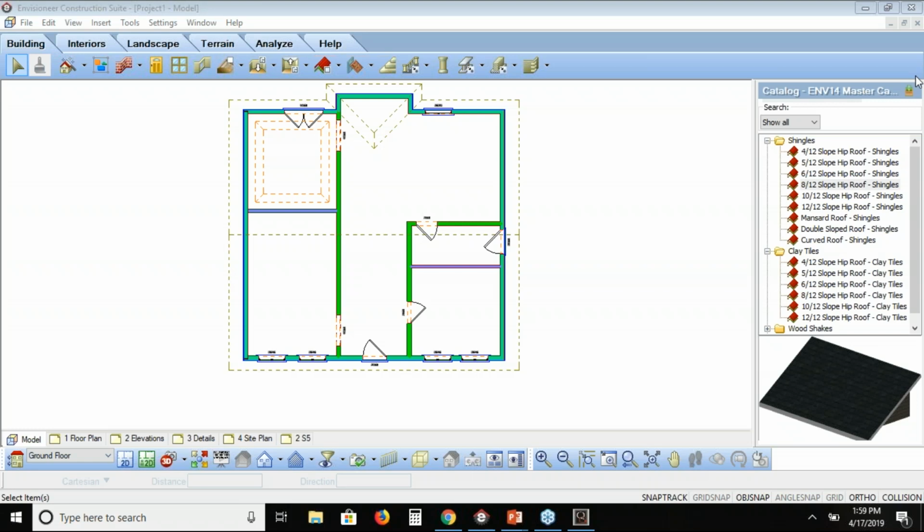Also, is it possible to frame the ceiling in a more practical way for span load concerns? Absolutely. So when you're framing the ceilings, it's just the same as I did with those joists for the floors. If I want them to go 90 degrees instead of front to back, those can be spanned in any span that you want them to be. They can stop at your load-bearing walls. Think of it the same as when I was framing out those floors. We can rotate the framing so it's going in a different direction. We can stop them at different walls if you need to as well. So yeah, no problems there.